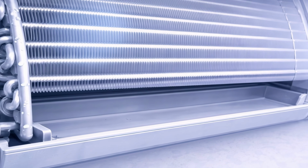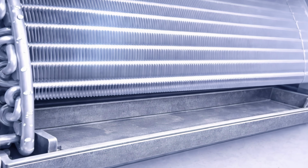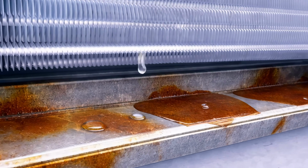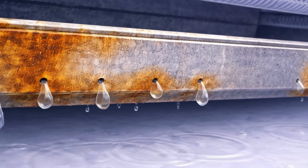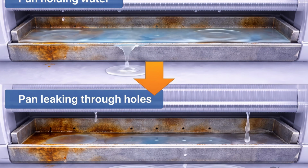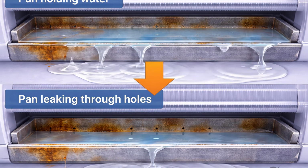We also have to look at the catch basin itself, the drain pan. In older systems, these pans were often made of galvanized metal. After years of constant exposure to moisture, these metal pans can develop rust. Eventually, that rust eats all the way through the bottom of the pan, creating pinholes. You might have a perfectly clear drain line, but if the bucket catching the water has a hole in it, the water will drip straight through.